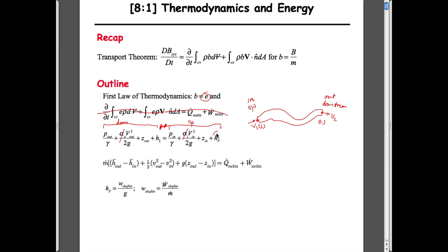The magnitude of the pump head, we know, is positive if it's pumping. It's negative if it's a turbine. If it works out that it's a negative number, then you're getting energy out of the system. And it's equal to the power in watts, the rate of doing work, which is why we write it with uppercase W, and it's equal to the volumetric flow rate times the unit weight of the fluid.